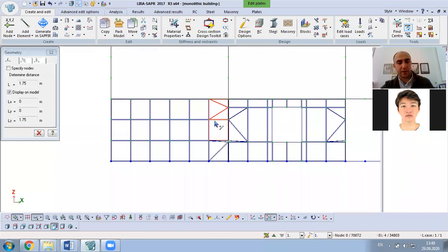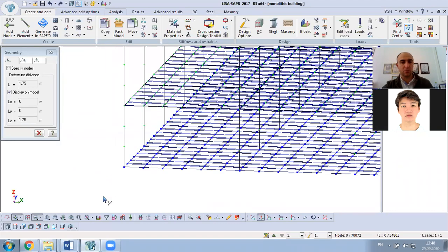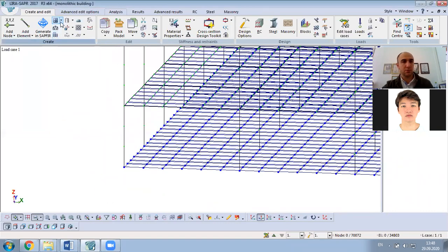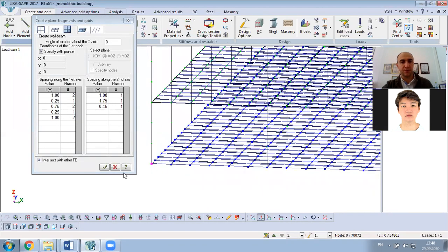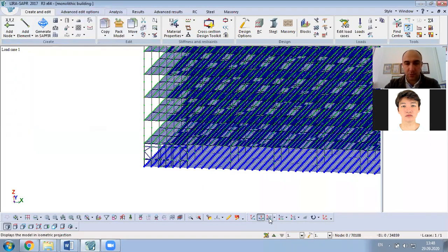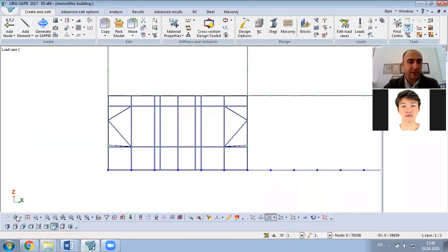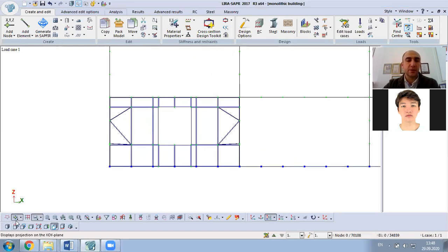Or maybe I can go back and start adding from the first wall. I will apply the wall and will show the first node. So I have already added the wall, and here I can delete the opening by selecting it. I select it by using nodes and bars, select my window and delete it.